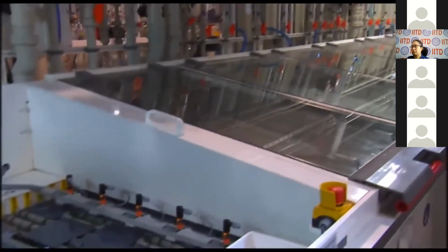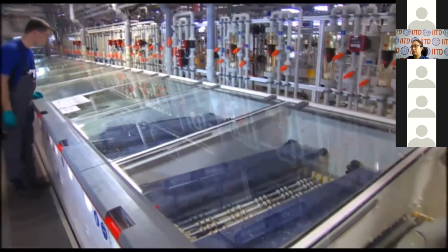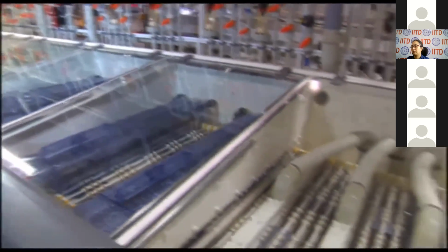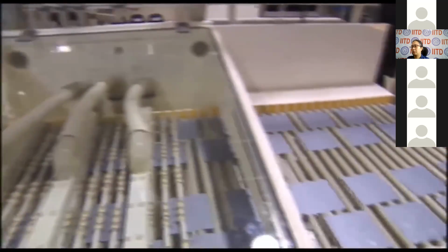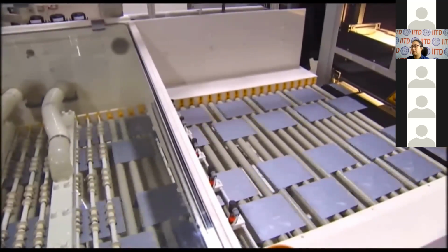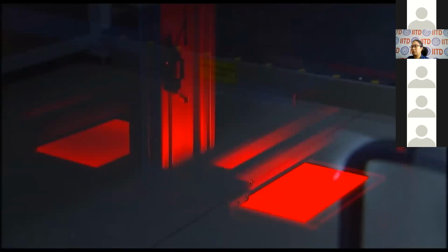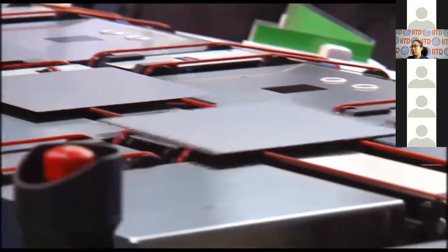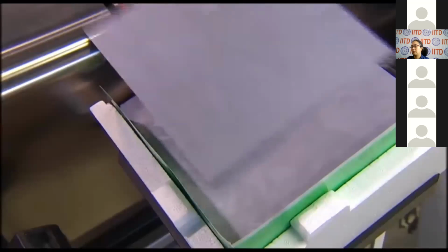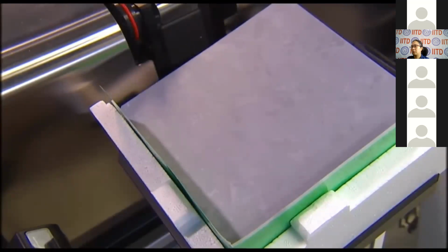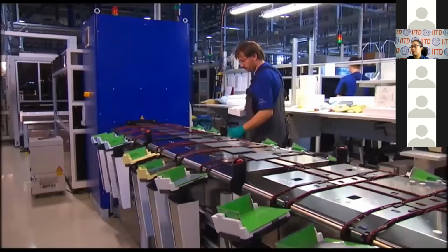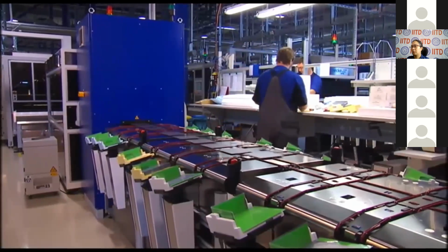Next, the wafers are isolated and run through further cleaning lines. Various surfactant and water baths, and the subsequent drying process, ensure optimum surface cleaning. All wafers are then measured by fully automated sensors and cameras and graded according to their thickness and surface quality. As base elements in solar cell production, multicrystalline wafers are subject to very thorough final inspections.